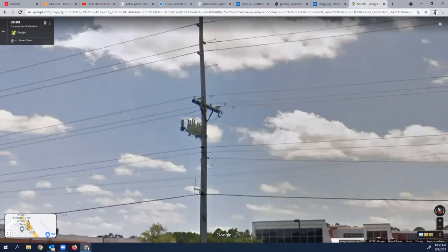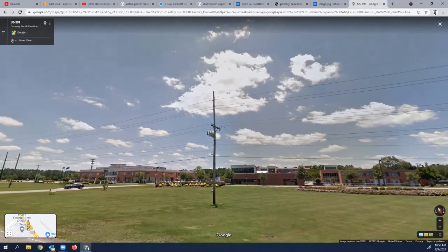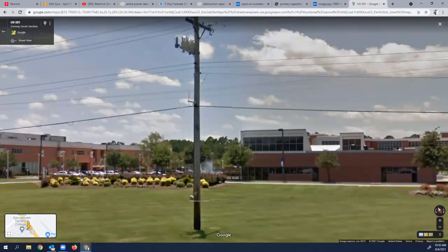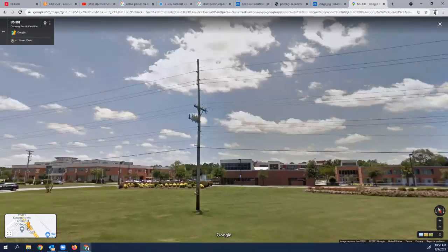The switches are closed. When I say move to a safe distance, I'm probably going to come 30, 40, 50 feet away in any diameter around the pole. That's what I mean by safe distance. Okay, stay away from it. If I've got that option and the capability to close something by SCADA, use it to its benefits.